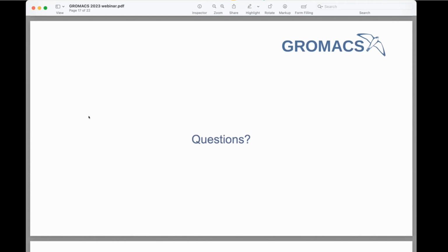Yes, I answered in the Q&A already that I suppose it works for many coarse-grained models if they're quite close to atomistic, like Martini. It's probably okay, but I'm not aware of the recommendations of Martini itself. Unless it's very coarse-grained, I think it should work. You can make these times a bit longer, but not that much longer. I think it is relatively uncritical nowadays with these first-order coupling algorithms. Tau p could need to be longer for things like membranes, which might have very slow modes, but even then, with first-order coupling, it usually works out. So it's far less sensitive than Parrinello-Rahman pressure coupling.